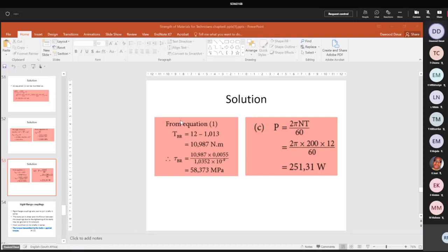Right? They're explaining to you how to get the formulas and all that type of thing. There's the hoop one with circumferential stress in megapascal. So it's Pascal, PD upon 2T. P is the pressure. D is the internal diameter. 2 times the thickness, which is the wall thickness in meters, eh? In meters, right? They're explaining to you how you get all these things. Don't worry about all these things. Only PD upon 2T, PD upon 4T. All right. Some movies and all here, they show you. They give you some examples here also in your book. Do not worry about all these type of examples like 14.2 where you got angles and all that. I won't ask you all that.